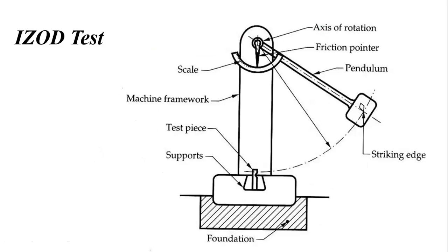There are several types of the impact test, and the most famous type is the Izod test. In the Izod test, a 10 millimeter square notched specimen is used. And it is preferred to use a specimen that has more than 1 or 2 and even 3 notches in the same specimen. The striker of the pendulum hits the specimen with a kinetic energy. This pendulum will hit this specimen, which is previously notched.